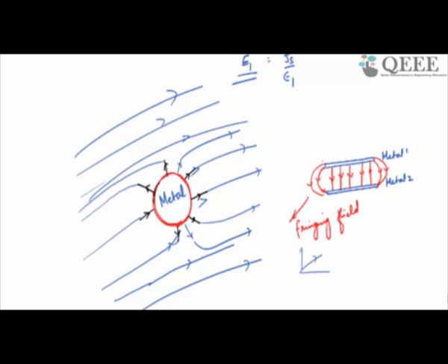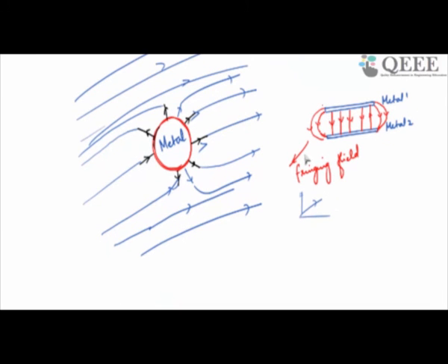Or in other words, if I imagine that these are the two plates of a microstrip line on a PCB, with a top plate and a bottom plate with which you are applying an electric field, you will see that there is an electric field leaking out, and this leaking out is simply to maintain the boundary condition. So you would definitely get some energy at the output. What's the problem with that?